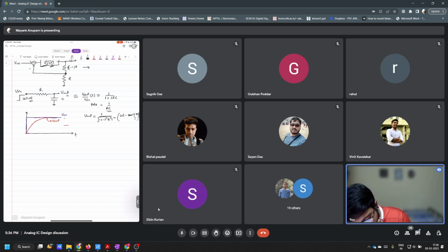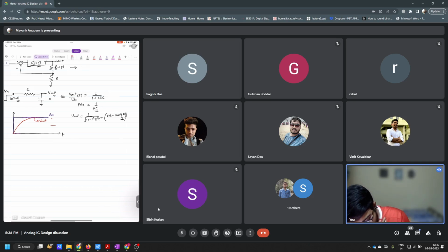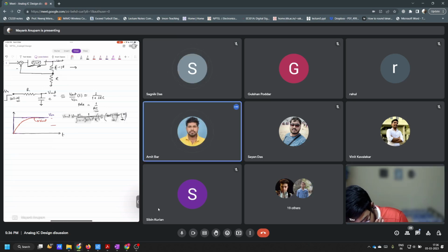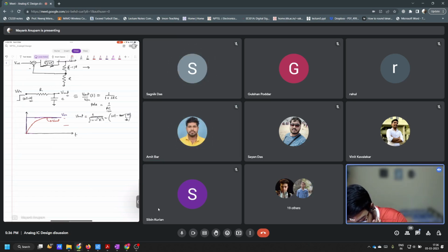So basically this is a phase delay, right? Are you with me or not? Are you understanding this part or not? Yes, sir. Okay, I require some feedback from you, otherwise I don't know whether you are understanding or not. So this is a phase delay, right? This is cos, by the way. So anything which is inside the argument of cos is phase, right? Omega t is also phase. This is also phase. So you can see that there is a constant phase offset. V in was cos of omega t, but the output is delayed, right? By tan inverse of omega RC.